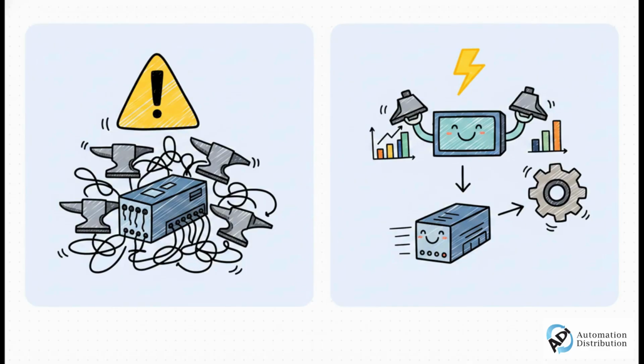So why is having that gateway role so critical? Well, in standard architectures, your PLC gets totally bogged down handling heavy data logs and trend analysis. That eats up valuable processing power that was meant for actual machine control. But by offloading that log creation and data processing to the HMI's quad-core processor, you free up your PLC to focus exclusively on time-sensitive control logic. It creates a much cleaner architecture and makes your entire system faster and significantly more reliable.